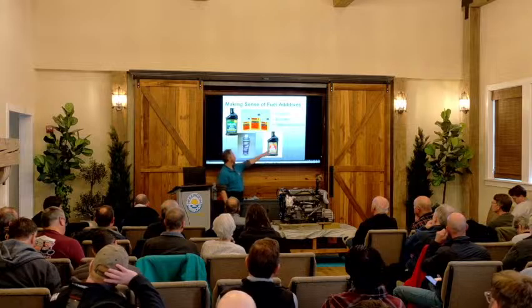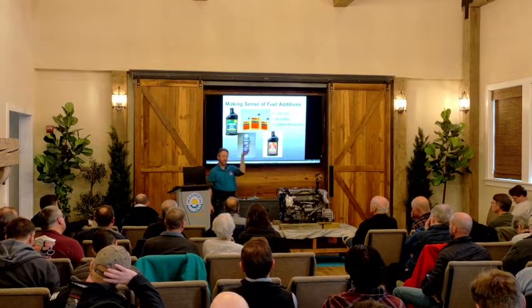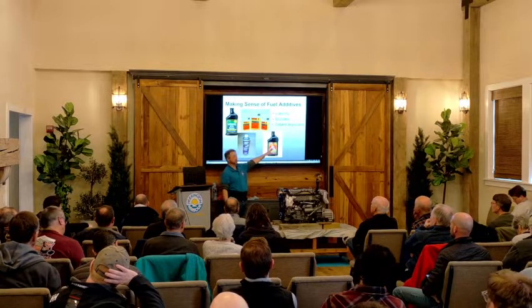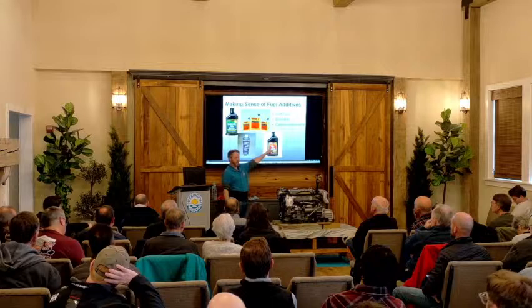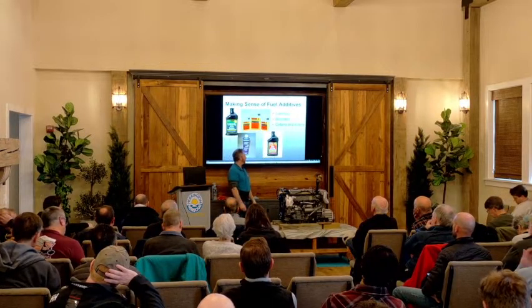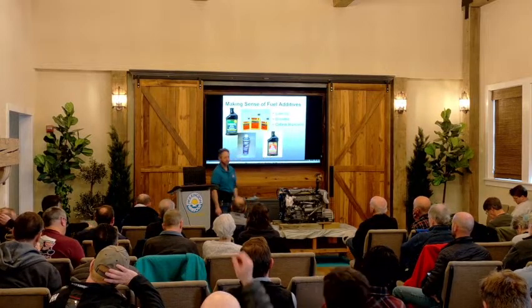So we can add a cetane improver and add more points of cetane back into the fuel. I have used this product and it does work, this FPPF. And this will add 8 points of cetane back into the fuel. So this one bottle will treat up to 250 gallons.